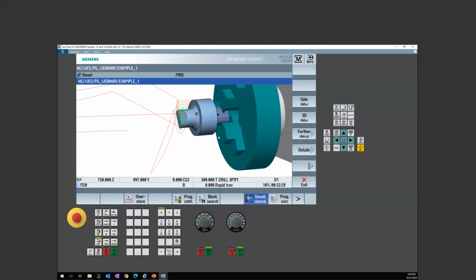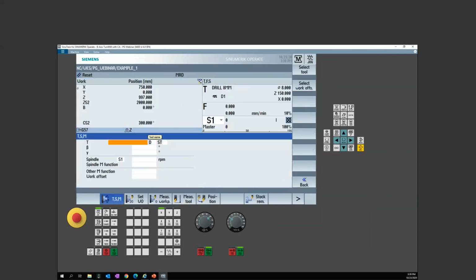So if you don't have that, how do I know I have collision avoidance? Well, other than getting this machine space model, when I'm back here in jog mode, you'll see these little sunglasses. This is always a dead indicator that your machine was set up for collision avoidance. If you have collision avoidance, then we can start to do a lot more with bringing in STLs. But by default, the standard simulation and editor does not support STLs.